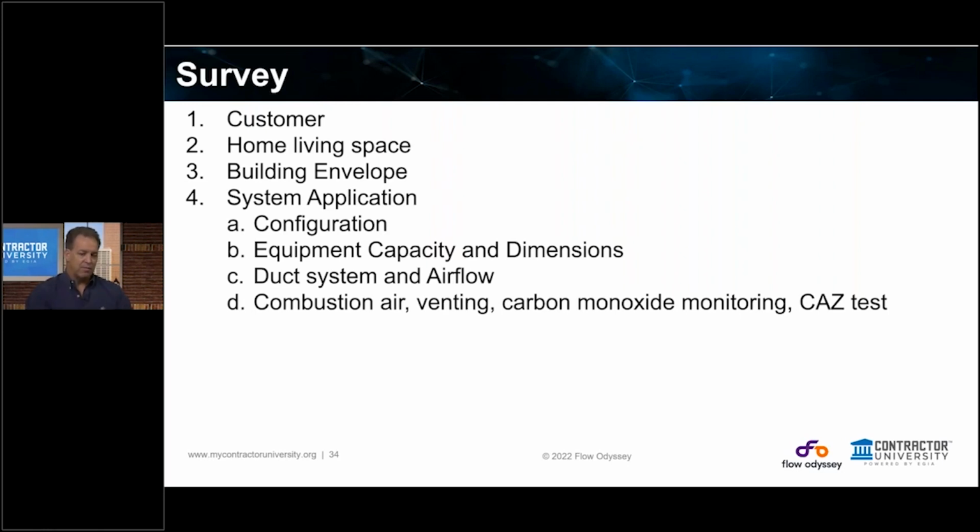And that's a lobby of those organizations that have worked with Washington to ensure that's what gets them that UL listing. However, you're not supposed to be sniffing carbon monoxide even at low levels, 5 parts per million, 15 parts per million, 35 parts per million, for any extended period of time. I've given you some information on carbon monoxide testing and facts you should know about carbon monoxide. Just because you have a crack in the heat exchanger doesn't mean you have carbon monoxide coming into the living space. But you need to understand the dangers of carbon monoxide and share that with a homeowner, not to put them in fear, but to make them aware.